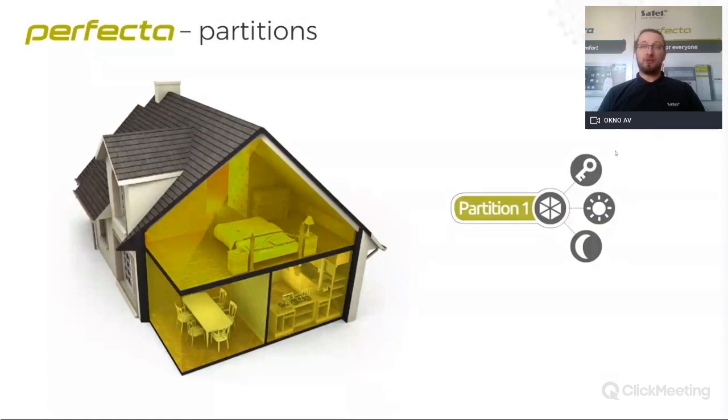And you can assign zones to each type of arming. Then, when you look at a keypad, you also have icons like day, the sun, the moon, etc. This gives the end user an understanding of what he is arming, for day or for night, and he can use his own code for it. So for most sites, you will use one partition, but of course you have an additional second partition, again, for a guest house, garage, or whatever you want, or a second house if you prefer, and of course with full functionality of different types of arming like day and night.